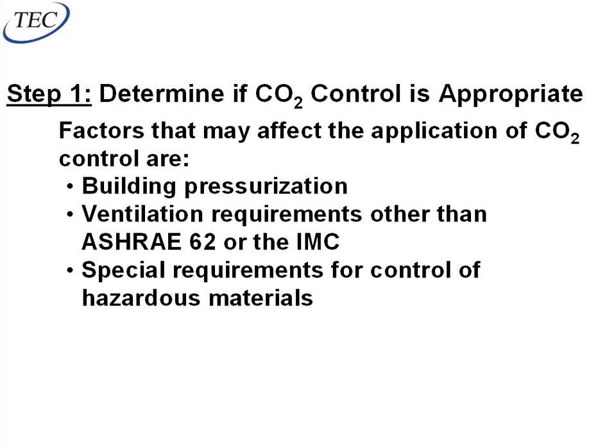All right, so when we're designing one of these systems, the first thing I want you to keep in mind is that all of the equipment gets designed exactly the same way as if I didn't have CO2. Because the worst case scenario is that everybody that this building was designed for actually shows up, and I have to ventilate for all those people. So my design day and my design equipment doesn't change. I have to still design it the same way for X amount of people in that space on a certain temperature day, and that's what I got to design it for. So all the equipment, everything stays the same, my loads stay the same.